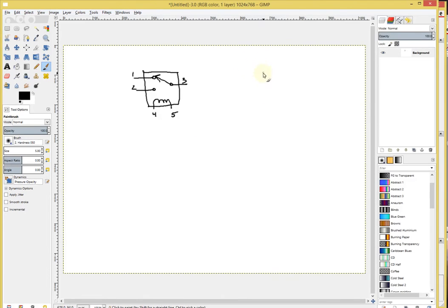First of all, you need to consider the physical dimension of the relay. Maybe it might be sort of like a rectangular box like this, right? And maybe you have 1, 2, 3, 4, 5, right? And if we look at the footprint for that, we might have 1, 2, 3, 4, 5. Okay, so this is what the footprint looks like. But just because the footprint occupies this much space doesn't necessarily mean that the part also occupies this much space. So you have to be careful.